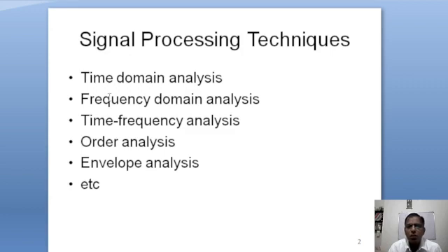In the previous lecture also we have seen there are various signal processing techniques by which a vibration signal or an acoustic signal can be processed, such as time domain analysis, frequency domain analysis, time frequency analysis, order analysis, envelope analysis, etc. Out of which in the previous videos we have seen time domain analysis and frequency domain analysis, and particularly fast Fourier transform we have seen in very detail.